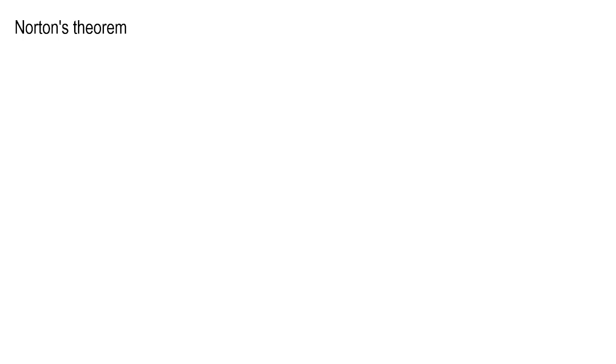Norton's theorem states that any linear network, listen carefully, any linear network can be converted to one current source IN in parallel with one resistance, that is nothing but RN. So this is N and we need to reconnect here RL.